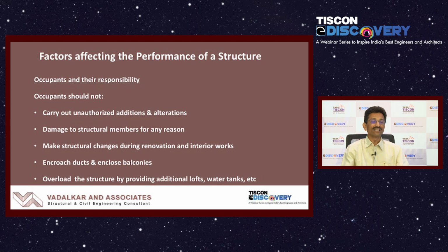So sometimes people cause damage during interior work; sometimes they just cut a core through the beam or the columns, which is really not desirable and should not be done. Damage to any structural member is disastrous. Making structural changes during interiors is also happening, and that is the reason for many of the collapses that happened in Mumbai and elsewhere. People have started removing the column in the building and the building came down.